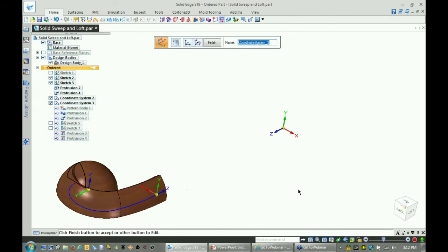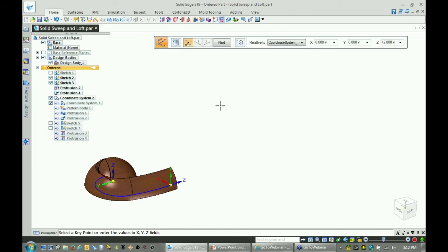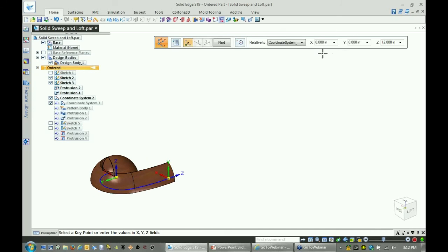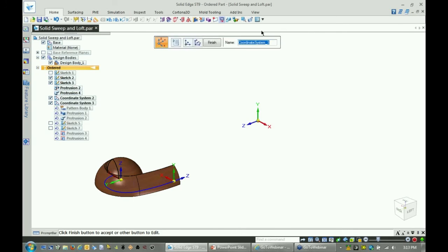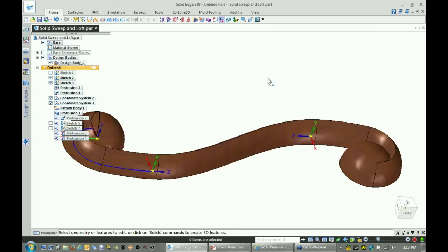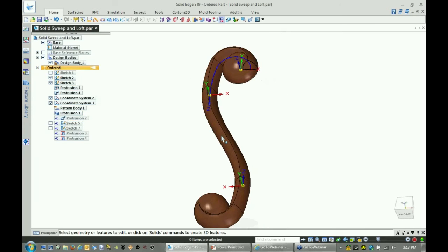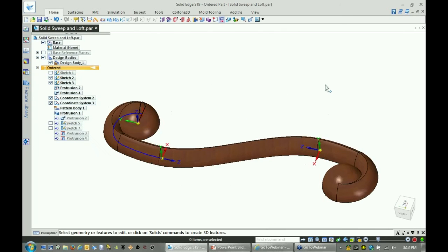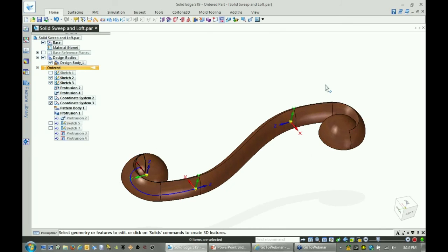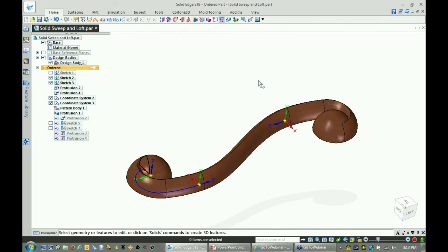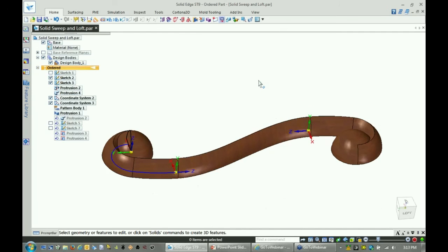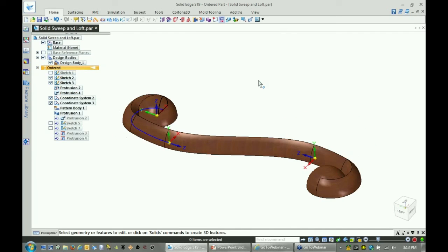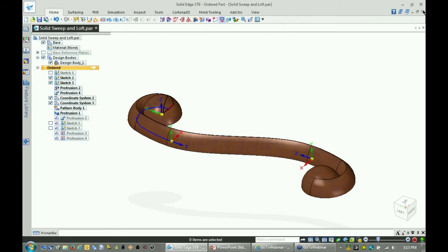And if I edit this duplicate XYZ coordinate, maybe I want to go in the X direction, like 4 inches. You can see how easily it adjusts itself and connects and continues connecting those pieces. So this is a great way to duplicate, and lofted protrusion is a great way to connect existing geometry in your design, or even use it from scratch when you wish to do that.